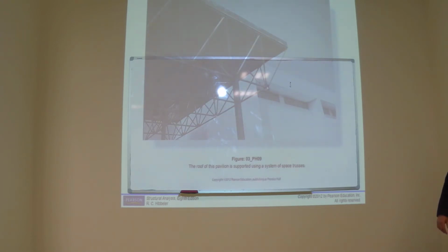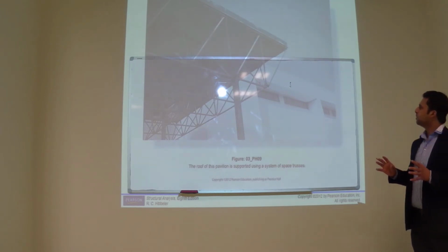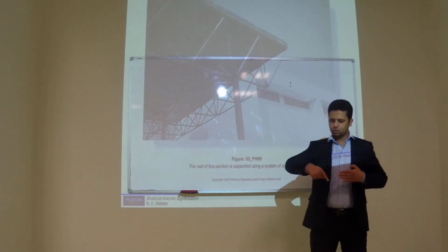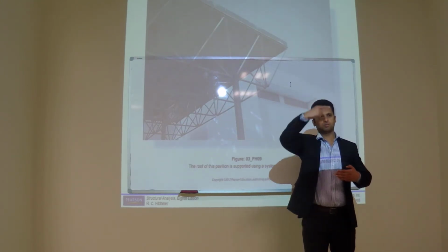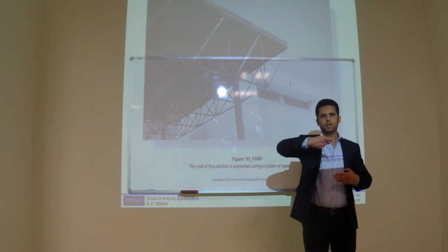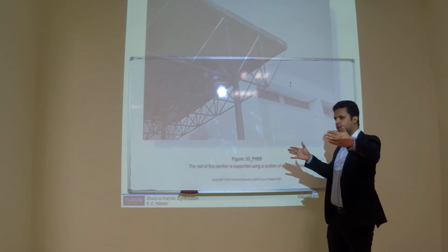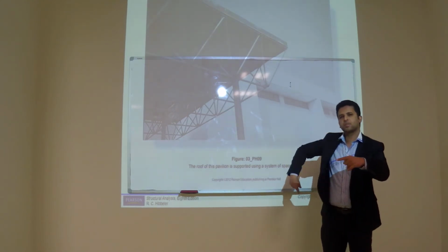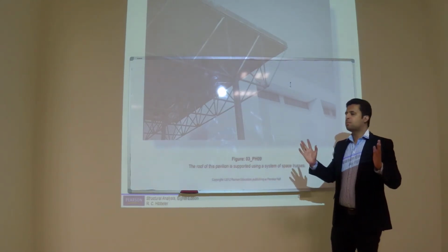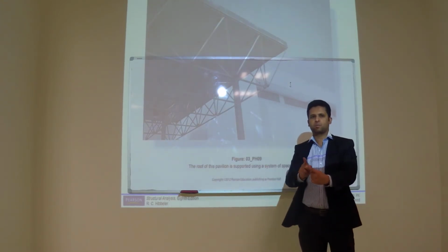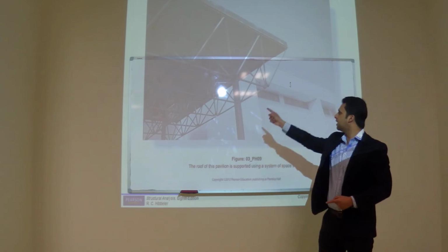And if you see that at each joint, the members are going in all three dimensions. Like in a truss, the members are in two dimensions, X and Y. Okay? One truss this way, one truss here, and you connect these two trusses by perpendicular members. But in a 3D truss, the members are projecting out of the joints and going in each direction.